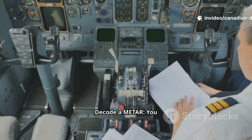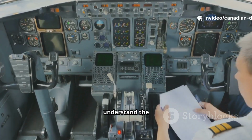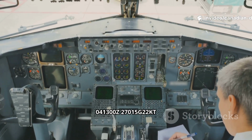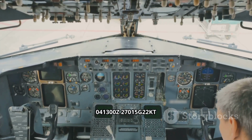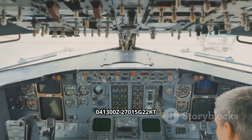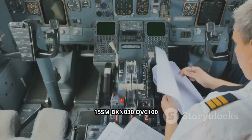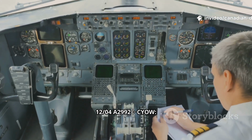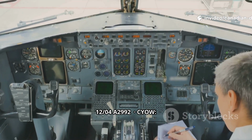2. Decode a METAR. You don't need to be an expert, but you should understand the basics of a METAR string. Example: CYOW 041300Z 27015G22KT 15SM BKN030 OVC100 12/04 A2992 RMK, Ottawa Airport.